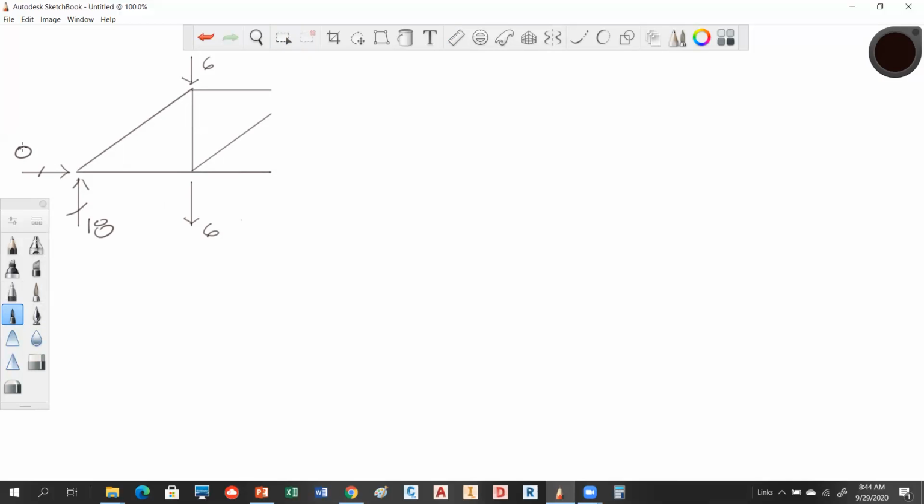Do I have any forces missing or any reactions missing? Any external loads missing or any forces missing or reactions? No. Is there anything that you think should be added? Like there's other forces out here, right? Sometimes people try to put those in. Notice those can't be in on this section cut, but they would be on the other one, right? Okay, so once you've done that, then you have to determine whether these guys are in compression or tension.